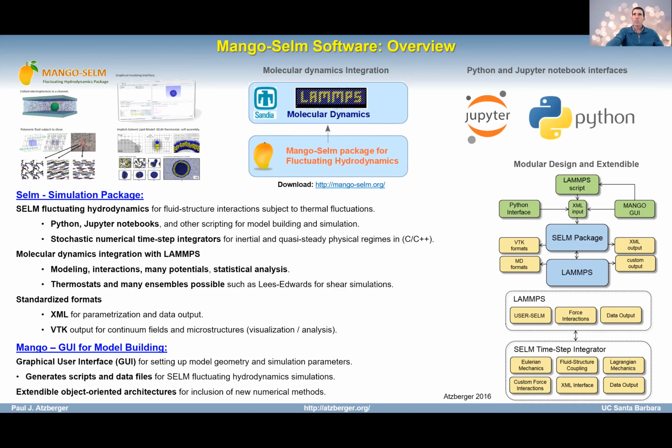Then there's a LAMMPS script, which traditionally was the driver for everything, but really now Python takes the place of this LAMMPS script and drives LAMMPS forward. And so that's going to be the paradigm that we work in: the Python script tells LAMMPS, hey, go look for these files, load them in, set up your state in a certain way, and then tells LAMMPS, hey, go run for 1,000 steps or so. LAMMPS returns its state information that gets passed back to Python, like the particle configuration.